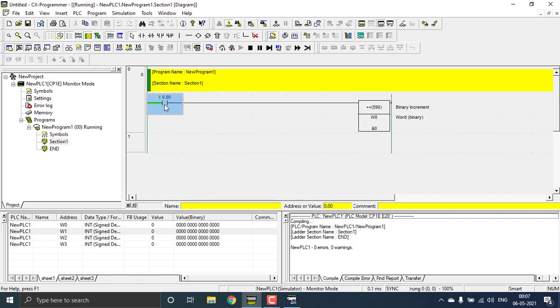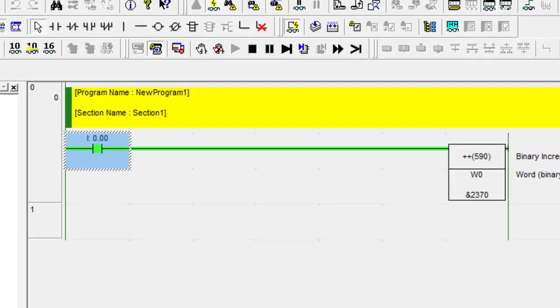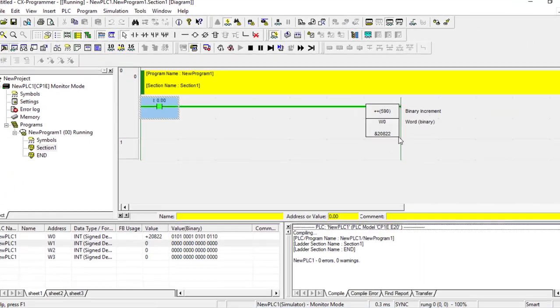And I'm going to start this controller or start the contact. You can see it is incrementing every 100 milliseconds. It is incrementing by some values. So it is reaching up to 65,000, which is the total value of the 16-bit word register, and it is again ramping up and down, up and down. The block keeps incrementing it.